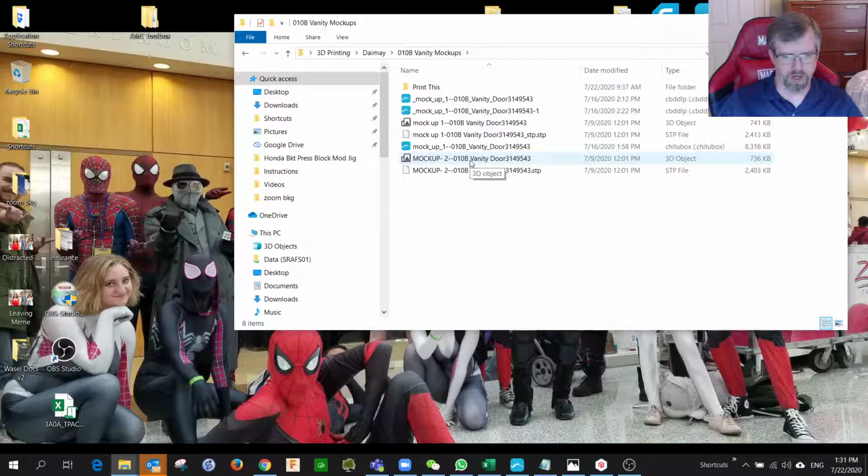So what you're going to need, from either something that you created or the engineer, designer, what have you, is an STL file. I sometimes request a STEP file as well because I know how to edit 3D files, and if you have some small changes that you need to make to what's being requested in order to make it more printable, that is sometimes faster than trying to go back and explain what you need. However, if you don't have that skill set, you don't need to really be concerned about asking for the STEP file. You need the STL file, which Windows recognizes as a 3D object.